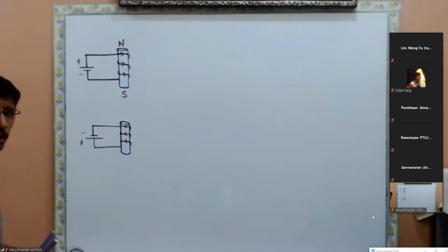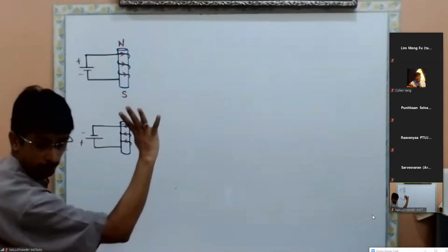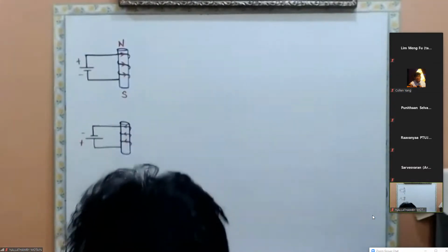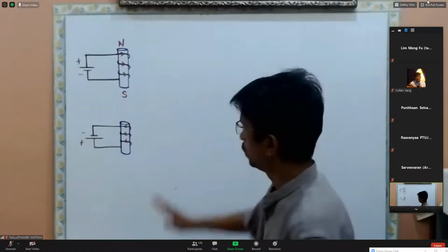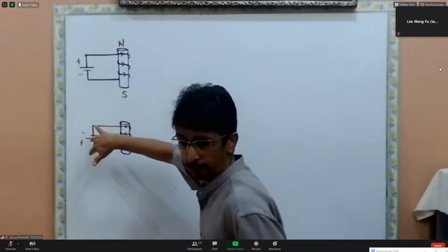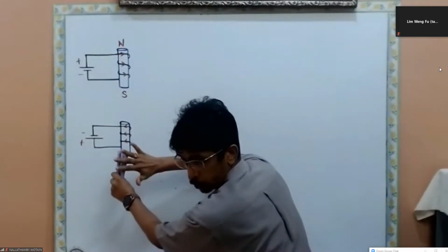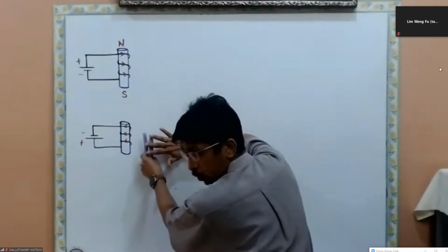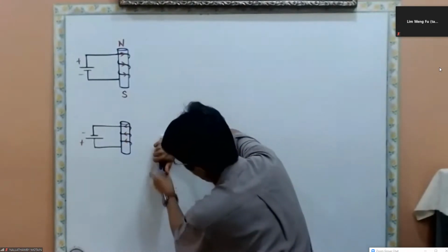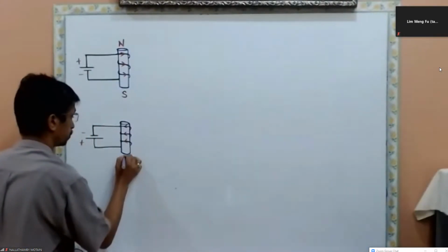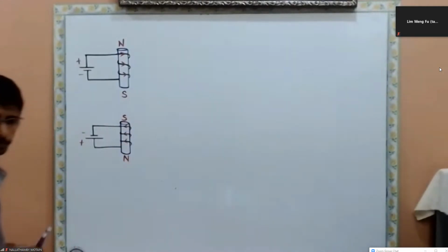Let's check using the right hand grip rule. Okay, your four fingers of the right hand over here, follow the arrow. It's in front to the left. Curl to the left, follow the arrow. So it is to the left, and your thumb points downward. Then here is the North Pole, and here will be the South Pole. So this is a way to identify the poles.